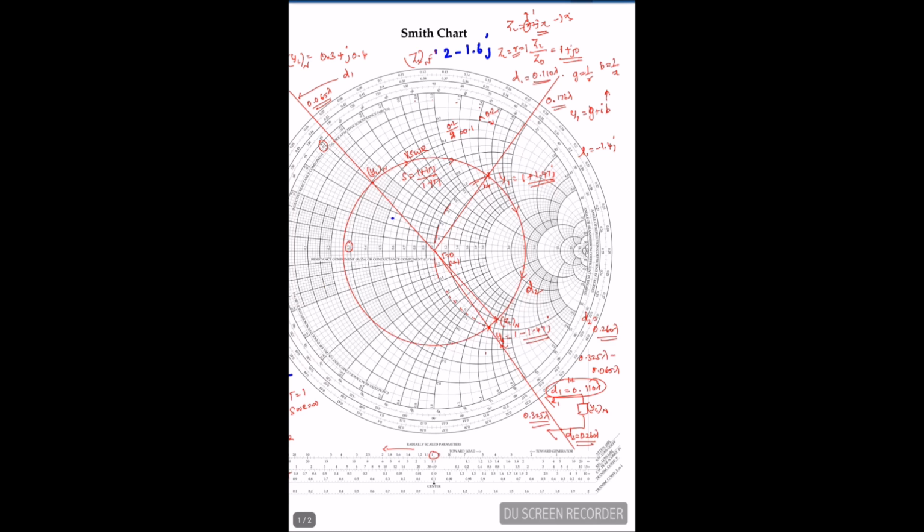So once I know the real part of the admittance, at that time I have to cancel out the reactance part. So for the first, y1, I have to choose the length of the stub with minus 1.4 j, and for the second distance I have to choose plus 1.4 j of susceptance, to cancel out this susceptance value in the new y1 and y2 values.